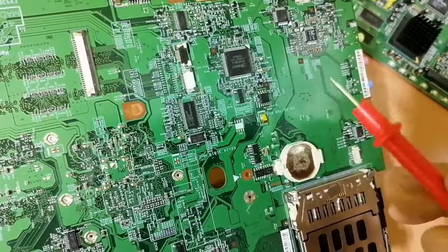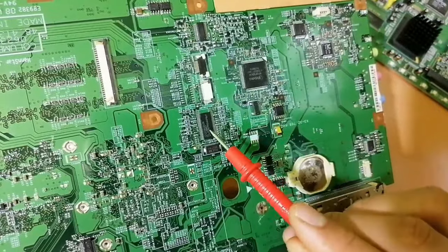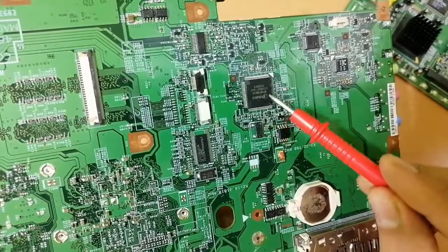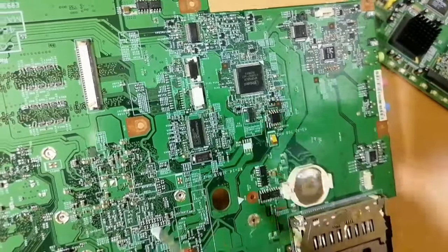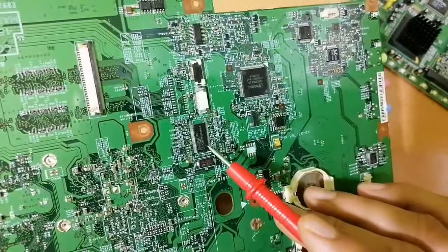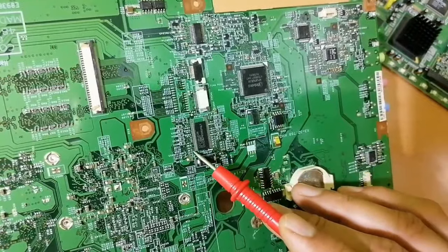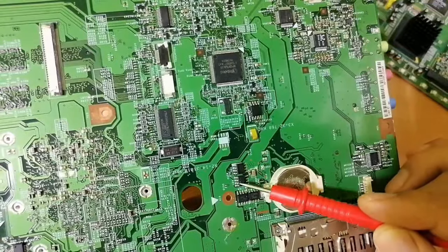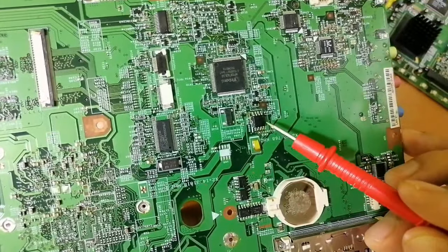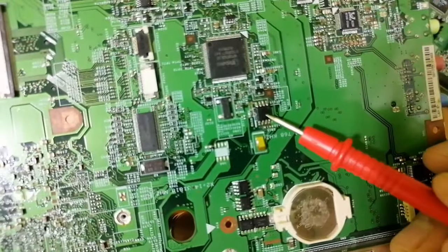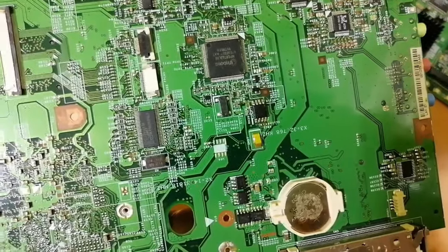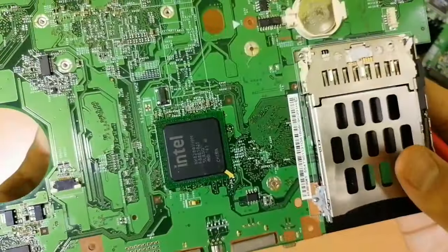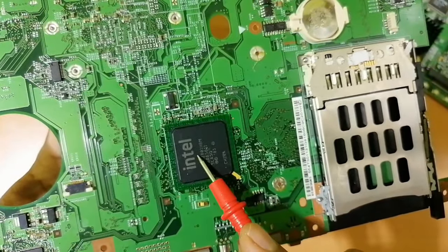As you can see here, the big components are always ICs, like this one for example. This is the Super IO IC. This is basically the laptop motherboard. Here we have the clock generator IC. This is the BIOS IC, and over here these are MOSFETs. As I told you before, the BIOS is always bigger than the MOSFET in terms of size. And over here we have chipsets, as you can see.